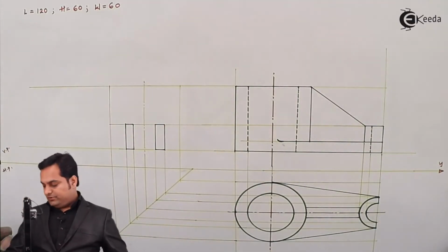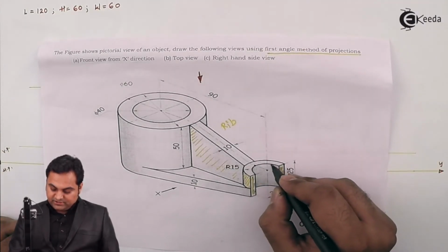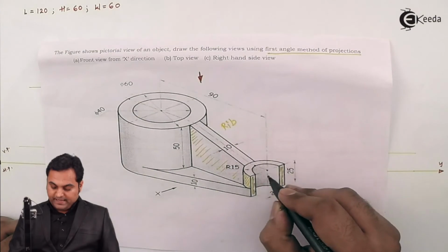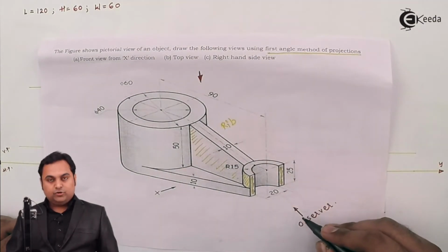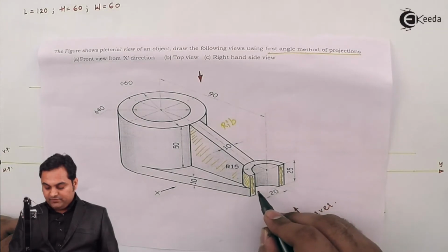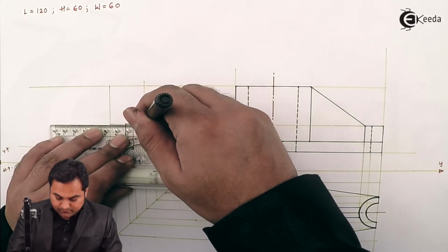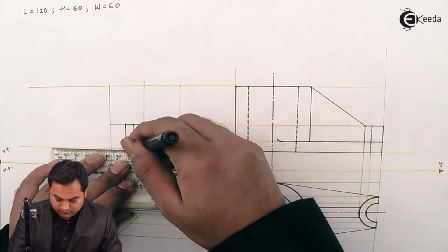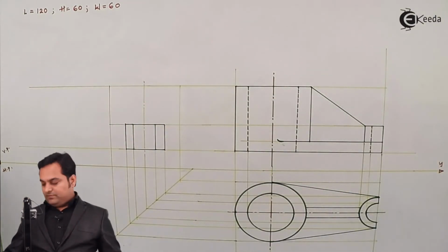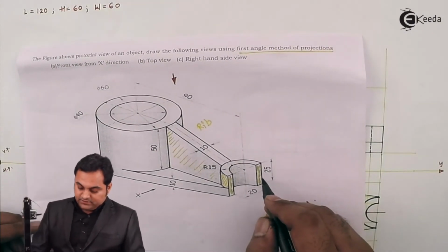Now after drawing these two rectangles, here we have an inside semicircle at the top and at the bottom. So when as an observer we are looking from the right hand side, there will be a dark line representing these two semicircles. So in this way the semicircular plate will look like with the rectangles.